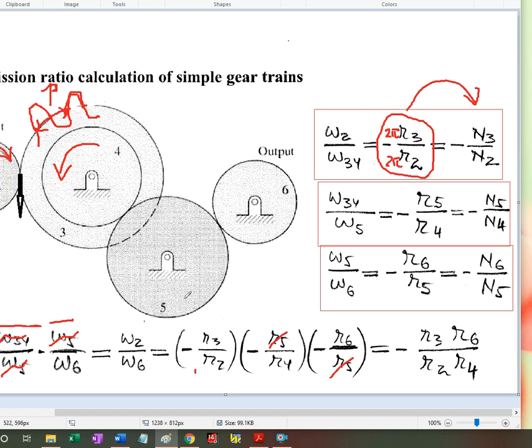So really the number of teeth or radius of gear number 5 does not matter, other than reversing the direction of rotation. So this is called an idler. You see it in a reverse manual transmission. When you switch into reverse, the motion goes through an idler.